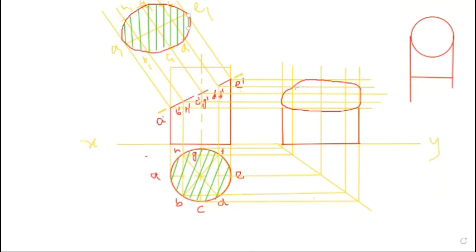Similarly here, this is also 45 degree in this way. This will be the circle basically. So in this circle, this will be the 45 degree. Here the gap is not proper, so you have to maintain the gap of 1 millimeter each. At 1 millimeter each, you can maintain the gap for the hatching line, drawing the hatching line.